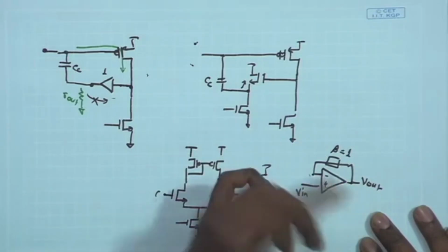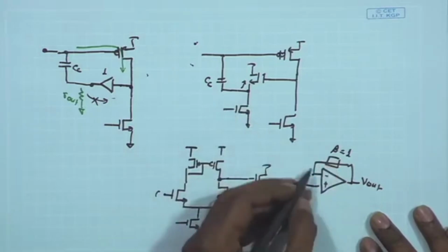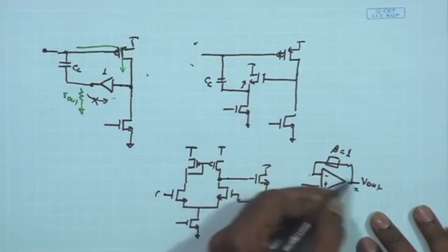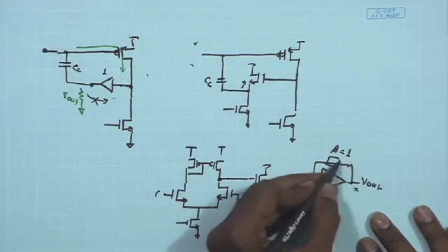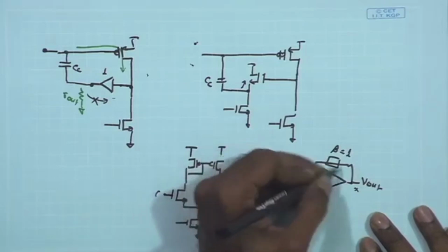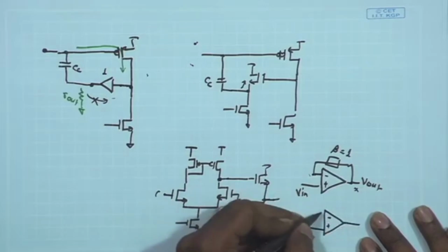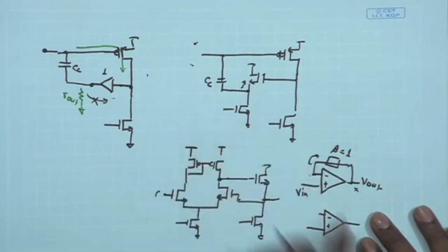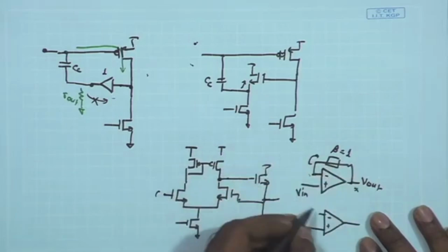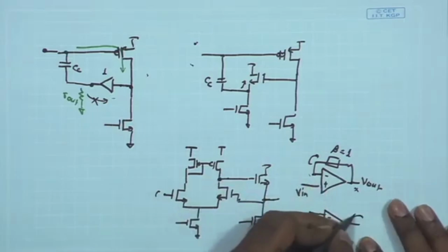And in order to find out the open loop impedance and hence the closed loop impedance, we know that we can just put an open circuit over here, because looking from the input port of the feedback network, I have a series connection at the output point. So, I can open circuit it, and looking at the output port of the feedback network, the other terminal is shunt connected. So, I can just short circuit it or put in an AC ground. This is the equivalent open loop circuit corresponding to the voltage follower, and now I know the output impedance for this particular stage.